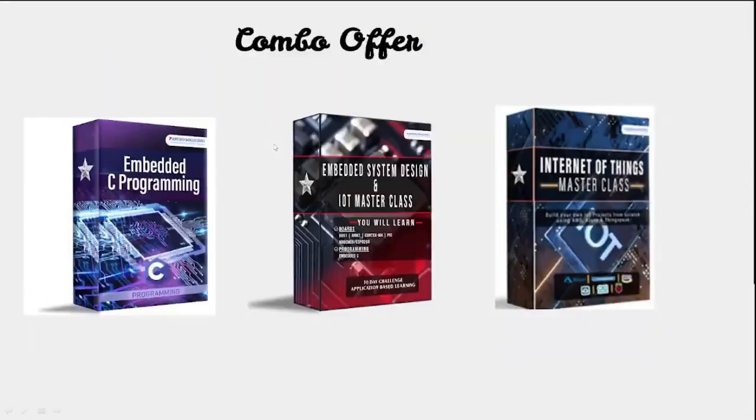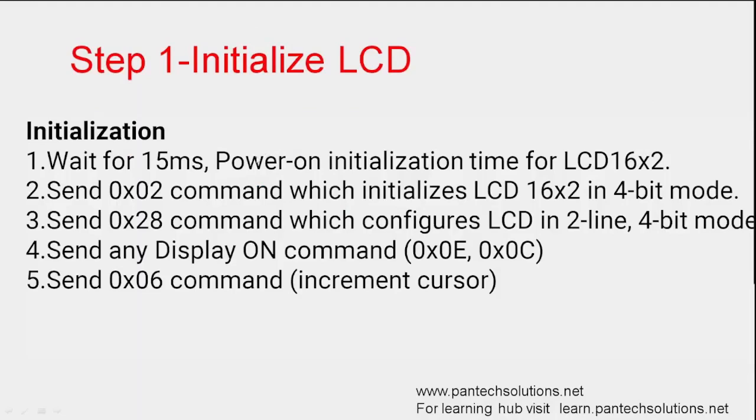Okay, so here are the steps. Step 1 is to initialize the LCD. You have to send the 02 command, which initializes the LCD in 4-bit mode, and the 28 command, which configures the LCD in 2-line 4-bit mode. Okay, 28 and 38, you have to check the datasheets. The display on commands are 0E and 0C, and the 06 command is to increment the cursor. You could get the command datasheets if you just Google for command datasheets of LCD. You'll get the list of commands available on the LCD.